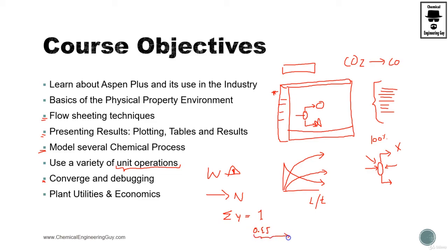Even though this is a small error, what Aspen Plus does is normalize all the values to fix the sum to 1. Say you have 10, 15, and 20, and we want them to add to 50, but technically they add to 45. Aspen distributes the missing 5 evenly, so you get values like 11, 16, and 23. 11 plus 16 plus 23 gives 50, so this is now correct. That's what I'm talking about with warnings.